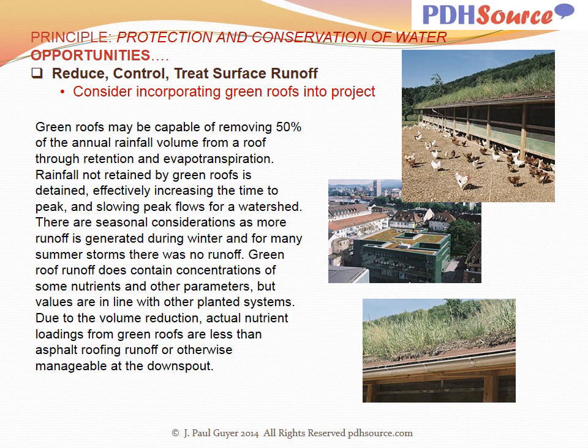Also with this green roof business, something you need to be aware of is that sooner or later you're going to have to replace the membrane on the underlying roof structure. So that means you're going to have to rip off all of this cute green roof stuff to get at the membrane. So a lot of cost there.